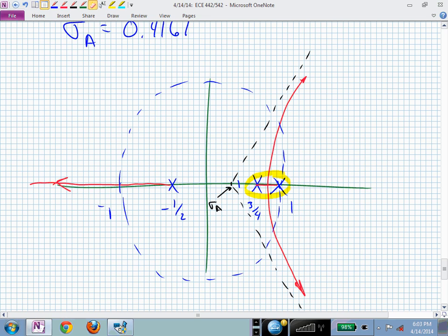This is with just a constant gain, isn't it? This red line is for a controller that consists only of a constant gain in a unity feedback configuration, and it produces these closed loop poles. As I crank up the gain K to 0.011, I get these two to come together and meet at 0.88. And then what about this guy here?